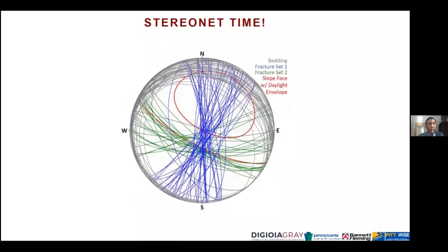And if you've been in a structural geology class or a rock mechanics class, you've likely seen STEREONETs before. A STEREONET enables you to take three-dimensional planar features and project them onto a two-dimensional polar coordinate system like this, and not lose any of that critical orientation data that we're after.